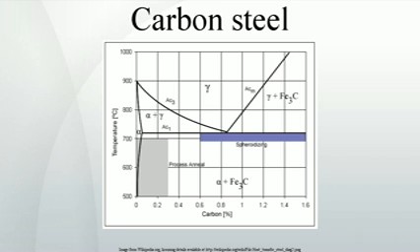Low carbon steel contains approximately 0.05 to 0.3% carbon, making it malleable and ductile. Mild steel has a relatively low tensile strength, but it is cheap and malleable. Surface hardness can be increased through carburizing. It is often used when large quantities of steel are needed, for example as structural steel. The density of mild steel is approximately 7.85 grams per centimeter cubed, 7850 kilograms per meter cubed or 0.284 pounds per inch cubed, and the Young's modulus is 210 GPa, 30 million psi.